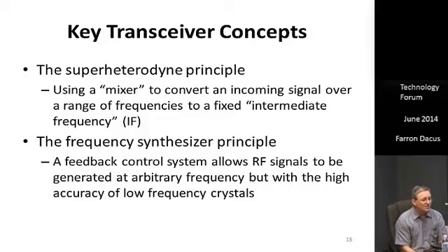Now, the reason this thing works so great that it's lasted 100 years and no end in sight is because of what I mentioned earlier. There's a lot of dynamic range in radio communications systems. So you're generally looking to get right down to the noise floor. And getting down to the noise floor means you need excellent filtering.